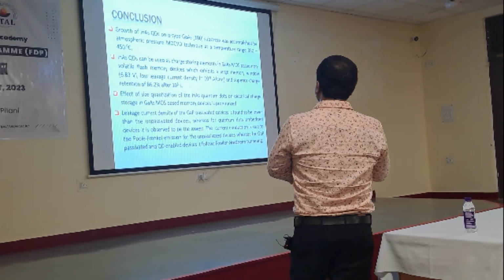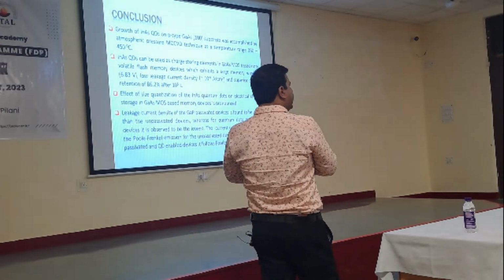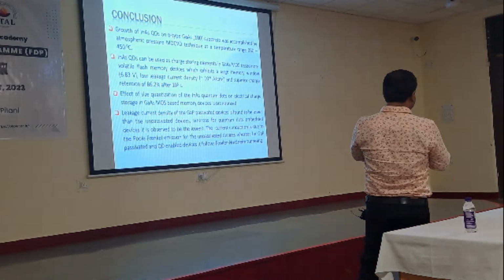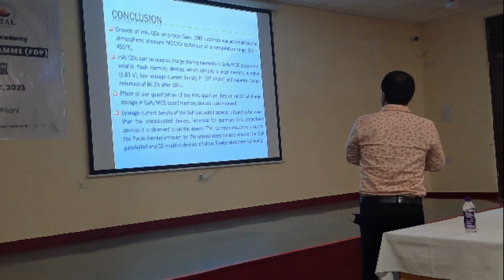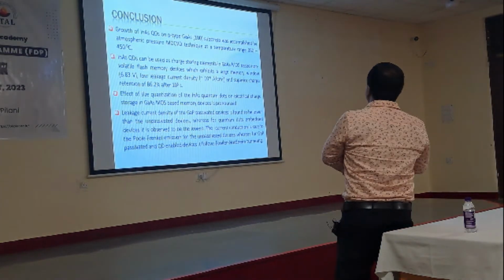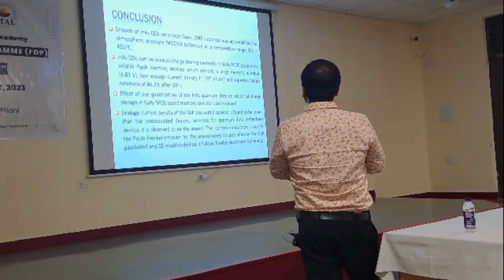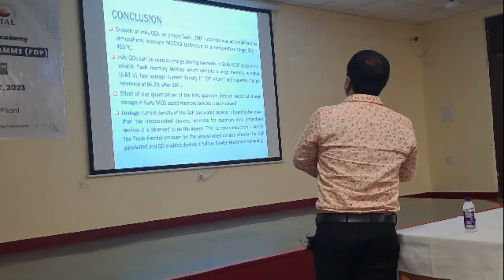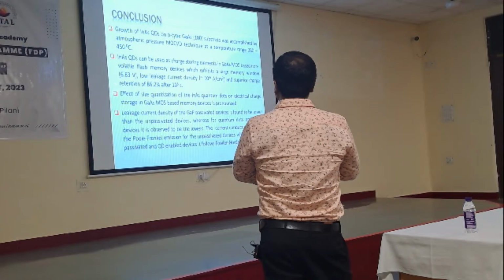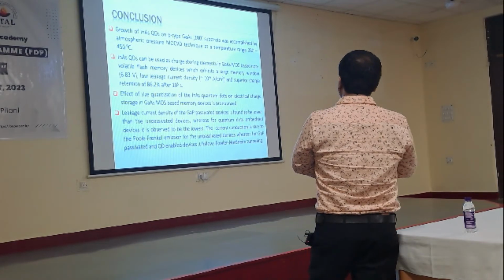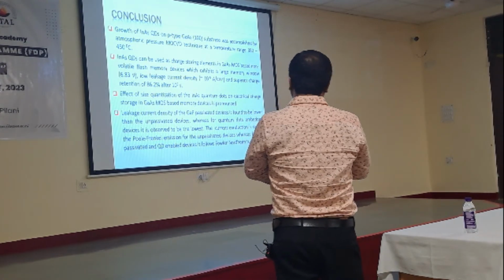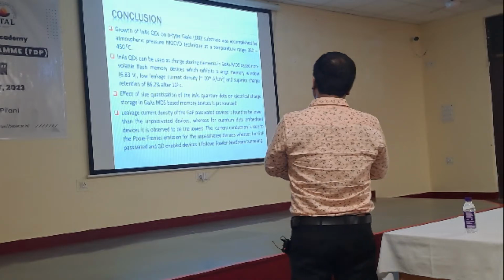So this is the conclusion actually. What is the conclusion? First of all, we have grown the indium arsenide quantum dots on bare gallium arsenide substrate as well as on a ZrO2 layer. Second, we have grown the indium arsenide quantum dots at comparatively low temperature, from 380 degrees centigrade to 450 degrees centigrade. You can see the maximum memory window, the large memory capacitance found is 6.83, a very low leakage current density in the range of 10 to the minus 6 ampere, and retention characteristics of at least 87%, even after 10 to the 5 seconds.